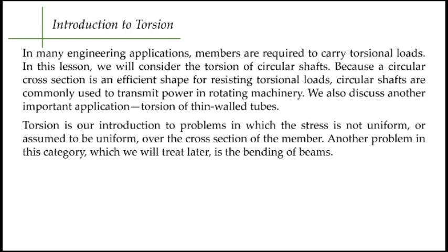Okay. Now, in many engineering applications, members are required to carry torsional loads. Yes, of course. But in this lesson, we'll consider torsion of circular shafts. But nevertheless, we'll also tackle, like I said, torsion in rectangular bars and how much shear stress will manifest inside a rectangular bar if it is subjected to a certain amount of torque, and what is the possible angle of twist. Now, because a circular cross section is an efficient shape for resisting torsional loads,